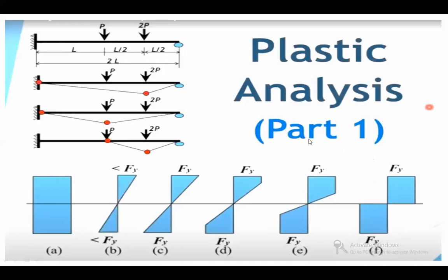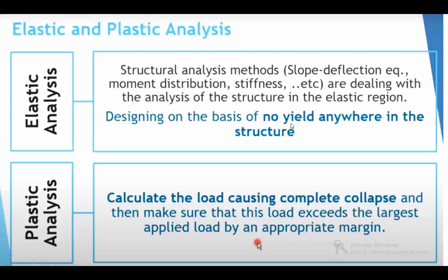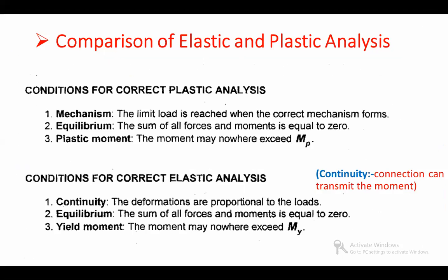Already you know that. Now what is elastic and plastic analysis? What is the comparison between elastic and plastic analysis? These are the conditions in plastic analysis. First is called mechanism, second is equilibrium, third is the plastic moment. These are the three conditions of a correct plastic analysis.